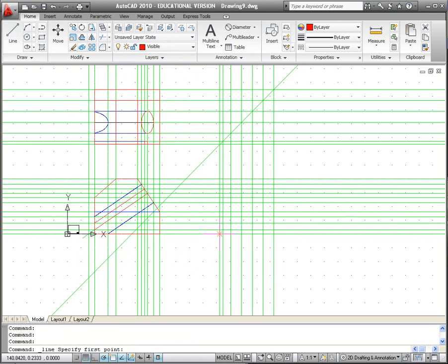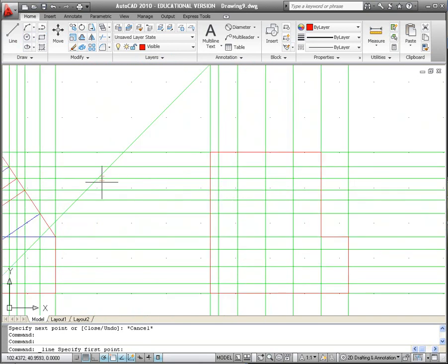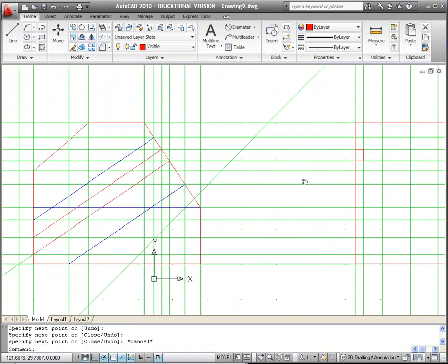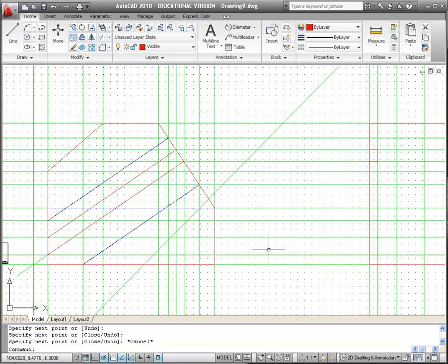So our block goes from here to here on the bottom. Then we come up and we have this indent on the side, come up to there, come across the top. We go down, and I'm going to go the whole way down, but you guys should be able to tell me what I forgot, and that's this corner, or this slot here. So where the slot goes in, we have this edge and this edge. And then there's also a hidden portion to the slot because there's this square back here.